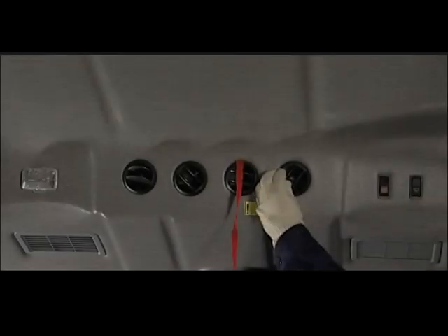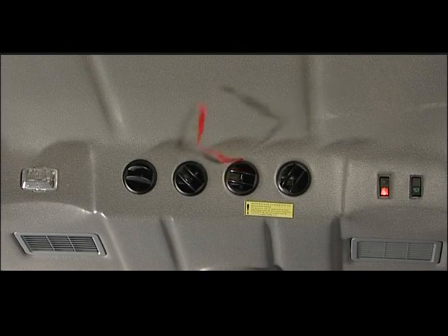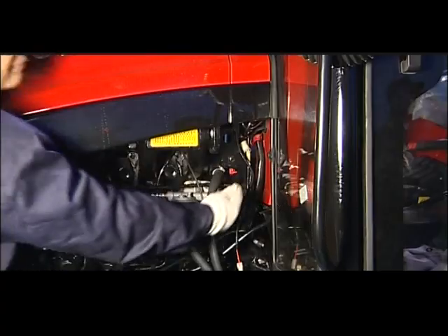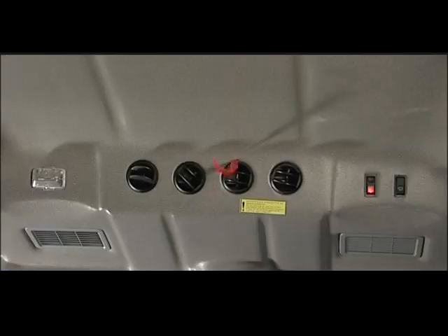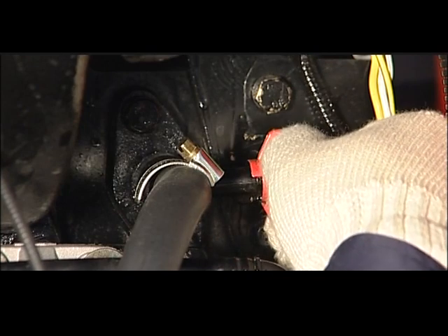Usage of auxiliary system. Warm air system can be selected to provide a comfortable driving environment for this series tractor, which consists of heating valve, heater, and system pipes. The customer may adjust the interior cab temperature based on the change of ambient temperatures. Close heater inlet valve when not used.